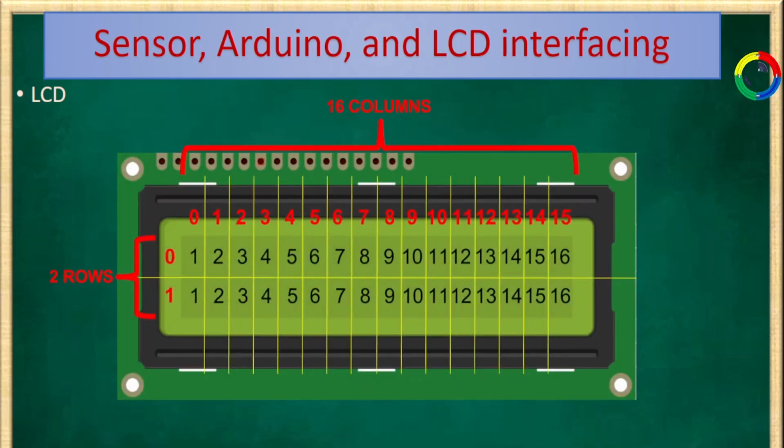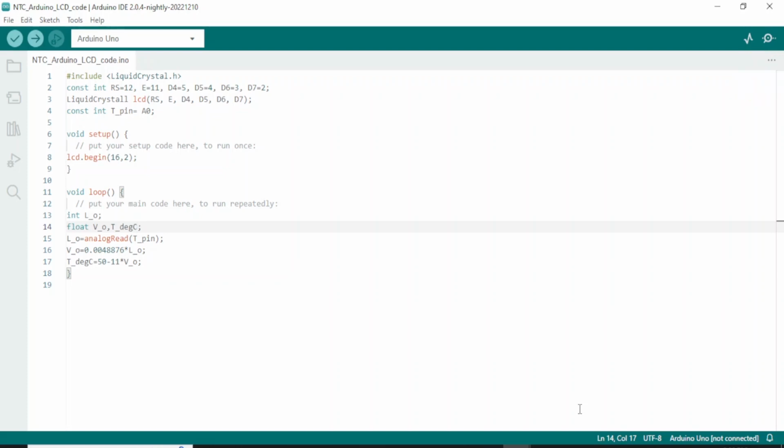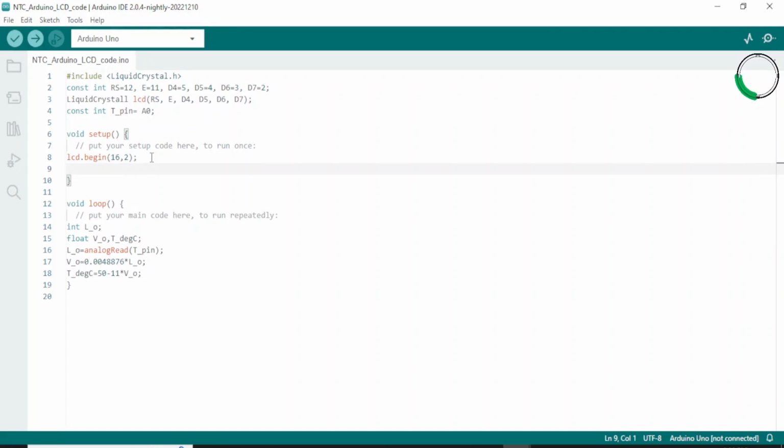As mentioned before, the LCD displays text in which each row contains cells. That is, there are 32 cells in total. The characters, punctuations, or custom characters can be written on each. Let's print some text on our LCD. Let's give our task a name by calling the LCD function lcd.print inside parentheses and in double quotations, Orion Tech Tube.